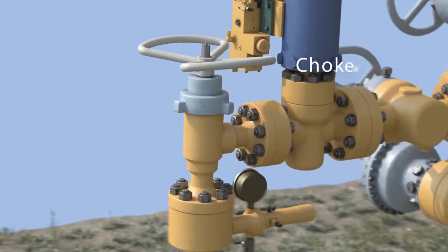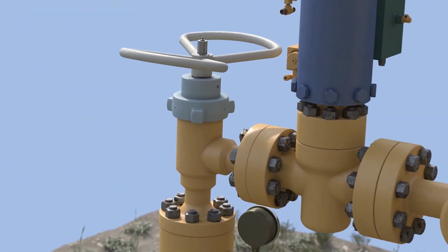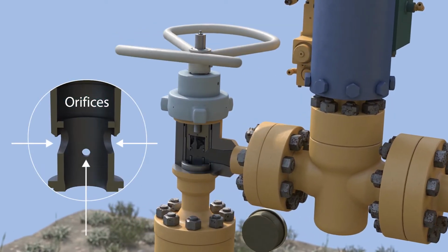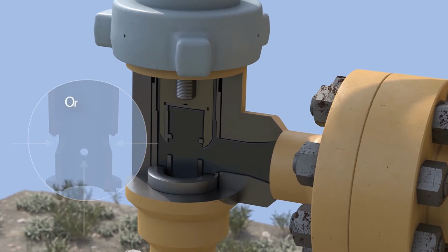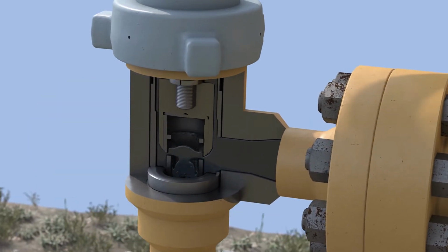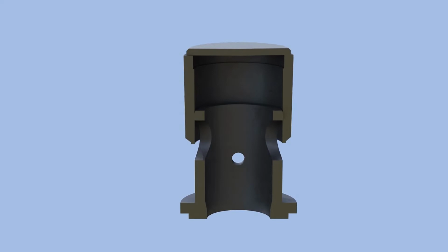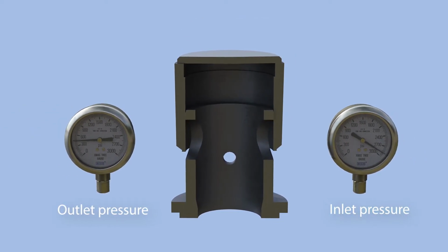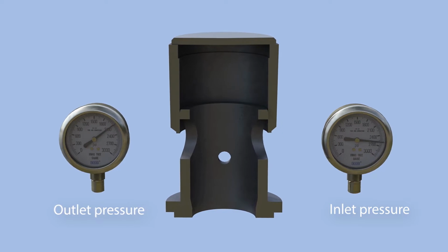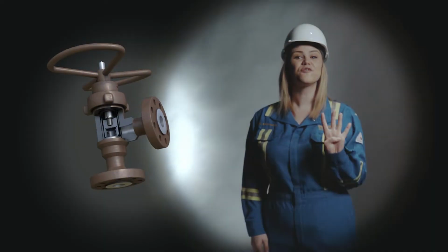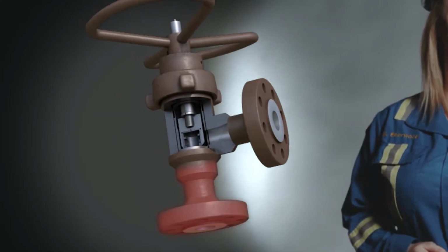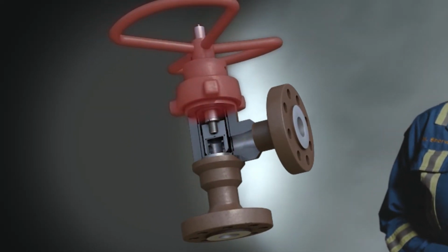The choke valve is designed to take the brunt of the pressure off of the line components, increasing their life and yielding significant benefits. By restricting the flow to a very small opening or orifice, choke valves reduce well pressure and control production rate, creating downstream or back pressure. There are four main elements of concern in a choke valve: inlet, outlet, trim, and throttling mechanism.